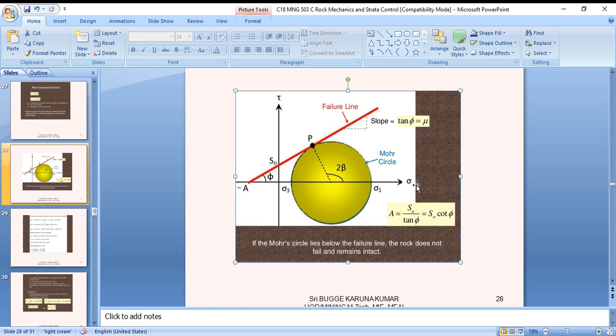If the shear stress is counterclockwise relative to the center of the element, plot tau xy below the normal stress axis, and if the shear stress is clockwise relative to the center of the element, plot tau xy above the normal stress axis. The shear stress acting on the other section is plotted above or below the point on the opposite side of the normal stress axis.